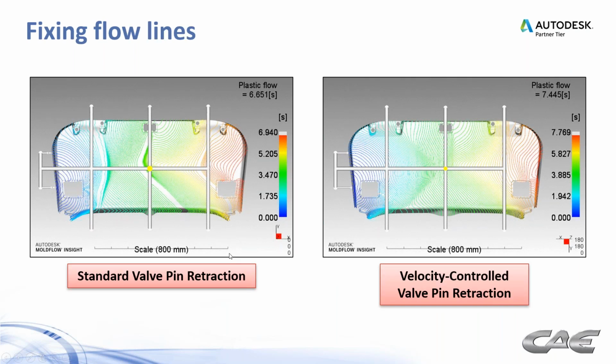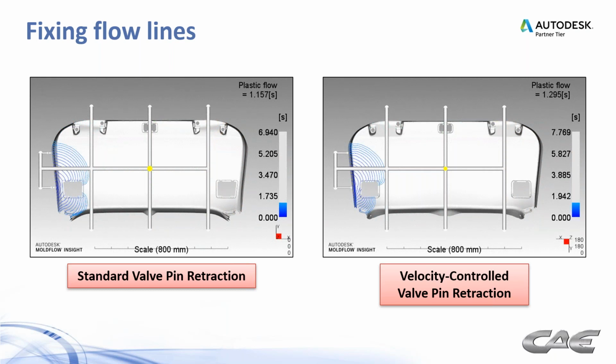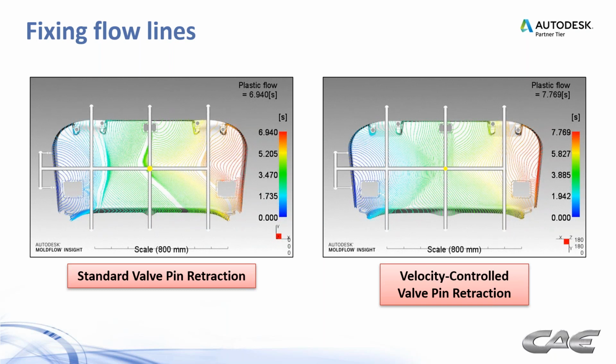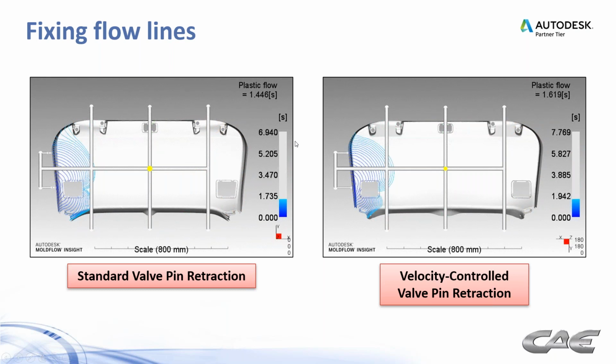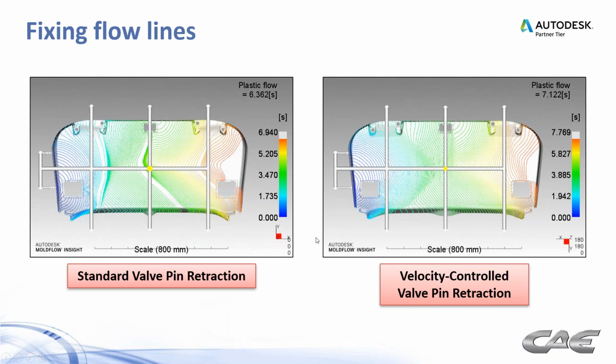And here's how it looks in Moldflow. So in Moldflow, we have the ability to time our valve gates however we want, either by flow front action, trigger, time. We can do it by position on the machine, screw position on the machine, lots of different ways to trigger valve gates in Moldflow. And now we have the ability to retract those pins slowly and control the velocity of the valves as they open.